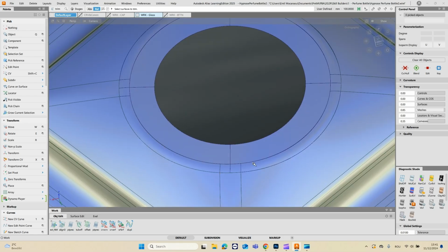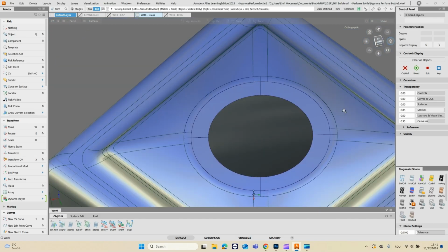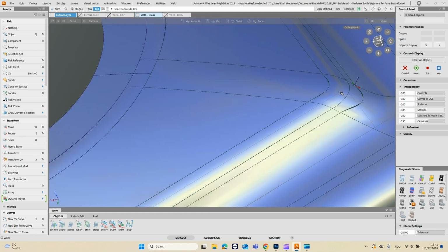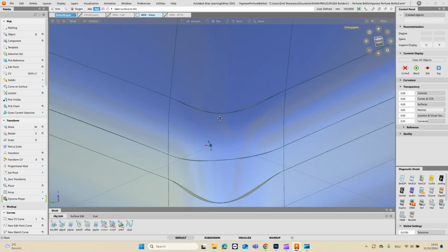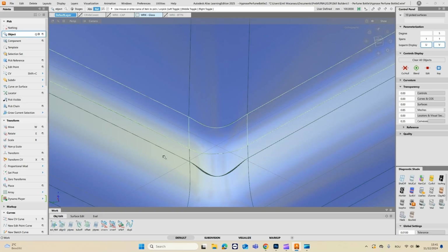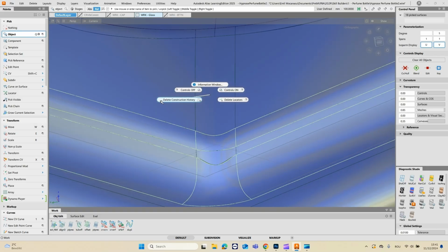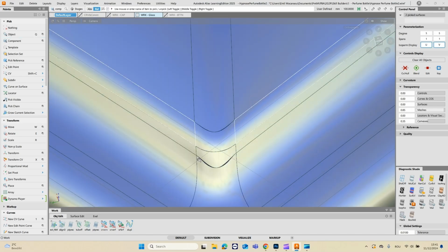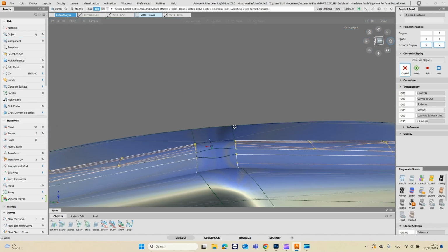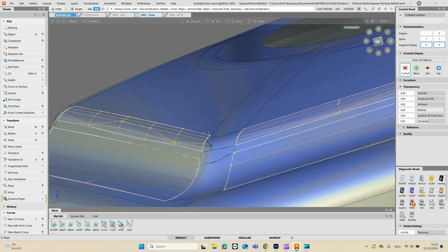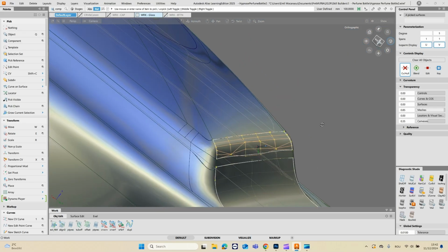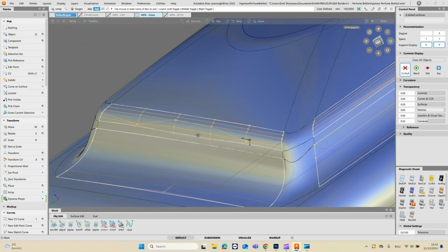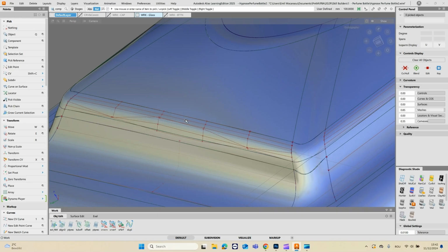So what I've done here, I would be doing on the other bits there. I'm not going to bore you with that. I want to show you how we fix that nasty CV layout there. For that, I'm going to take these two and delete their construction history. And we see that these are ending there, which is cool, but check that out. That's nasty on many levels, so let's take care of that.